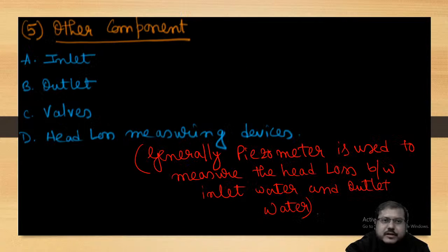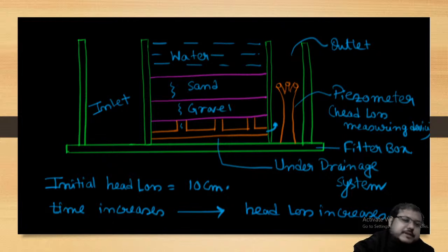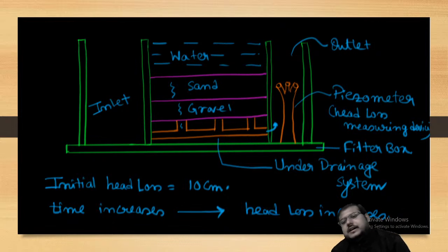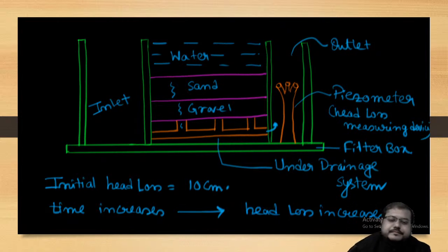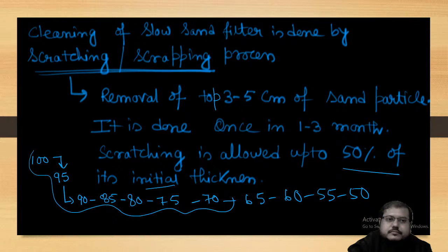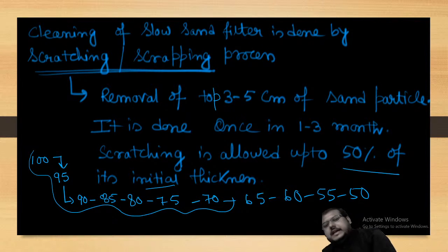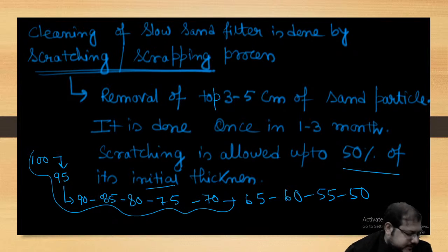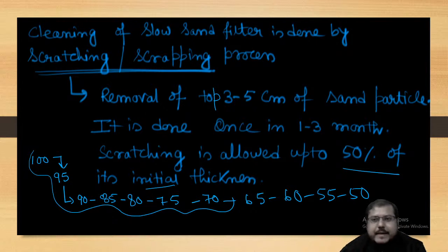Then we discussed how to clean a slow sand filter. Before that, we discussed the initial head loss and the terminal head loss values. And we discussed that the cleaning of the slow sand filter is done by the scratching or scraping process.